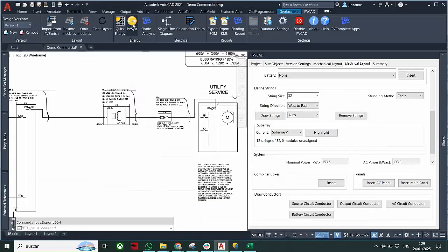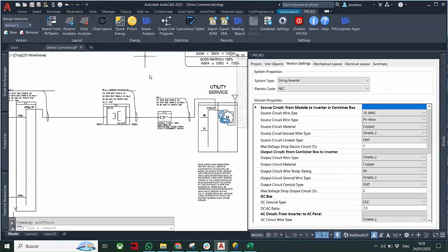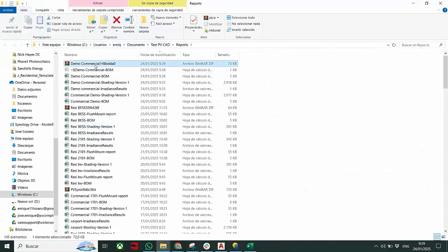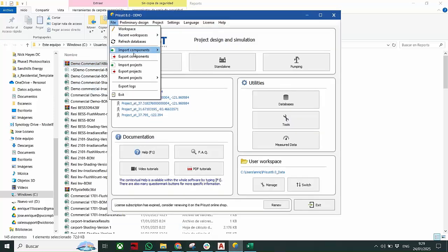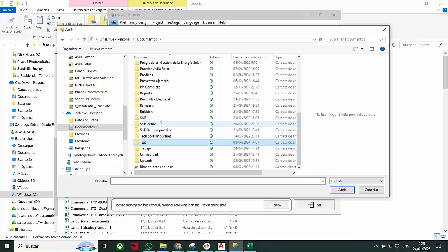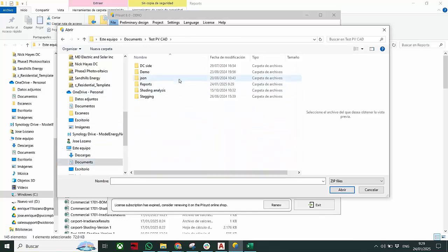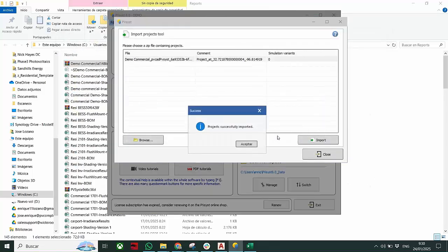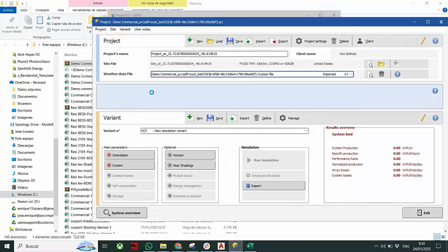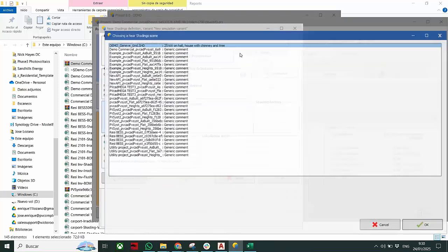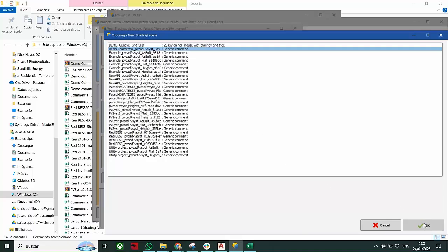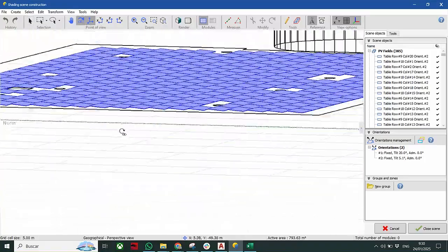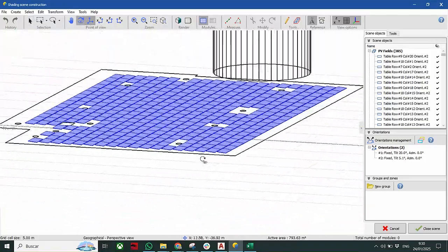The final feature I'm going to show here is our Export to PVsyst feature. So to activate this feature, I'm going to pick the PVsyst button from the top level menu, and this will cause the software to save the PVsyst compatible file onto your computer. Then if I go in and launch PVsyst, I can then, from PVsyst, find that project and load it into the PVsyst shade scene. And then I can get the full shade scene of the building that I modeled in PVCAD inside of the PVsyst environment.